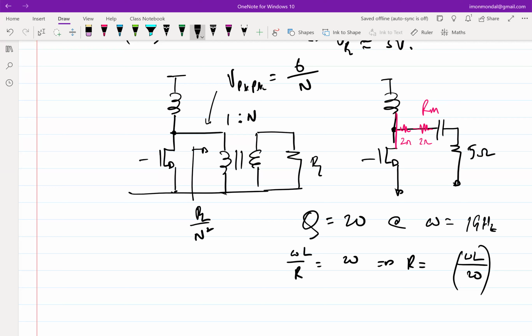Okay. So let's say you are not designing anything at 1 gig, you are designing something at very high frequency, like millimeter wave, 20, 30 gig, right? So then probably it's not a very good idea to put matching networks on the board, because you are not going to get very good Q with the onboard components, but you tend to get better Q with on-chip inductors.